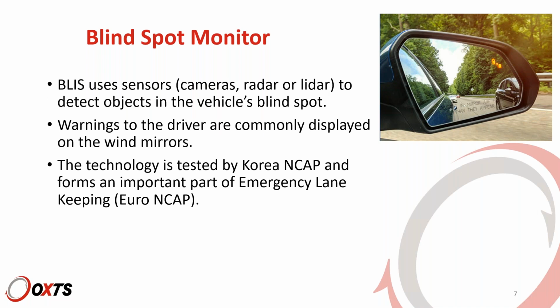Korea NCAP have a specific protocol for testing blind spots, but they're about the only NCAP that do. What generally happens is that it's a technology that's incorporated into more scenario-based things. So, for example, Euro NCAP have what they call emergency lane keeping. They have a few different scenarios that I'll come to, but one of which has an overtaking vehicle from behind.